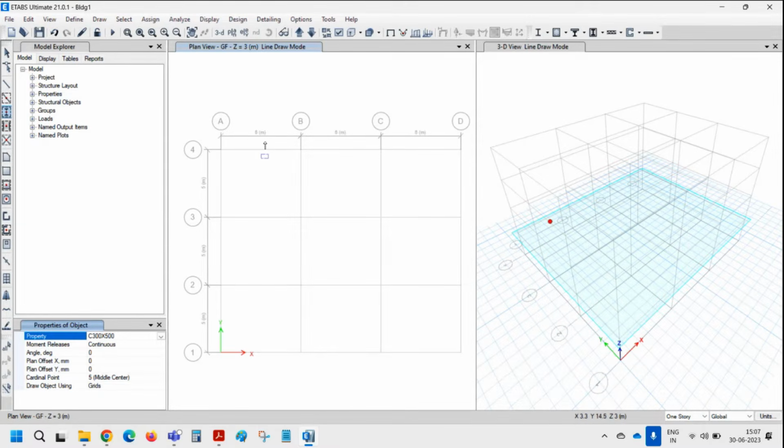So now you can see the vertical arrow, which represents the drawing mode. The regular arrow is not. As I move closer to a grid, you can see it snapped. And you click, and the column object will be created.